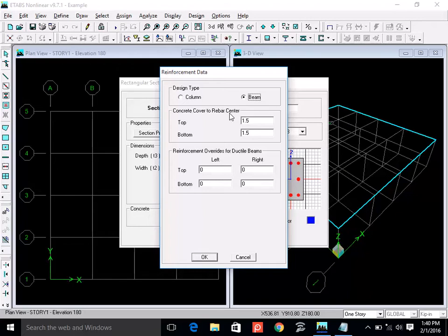Okay, look at this. You have the concrete surface, the soffit of the beam, and then you have shear reinforcement, and then the steel bar, the longitudinal steel bar. What this is talking about is, from the center of the rebar, this distance, which is equal to what?